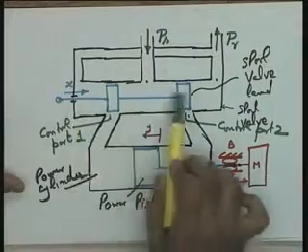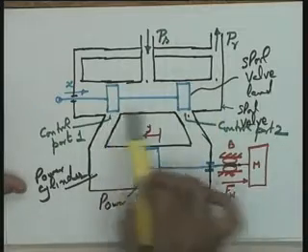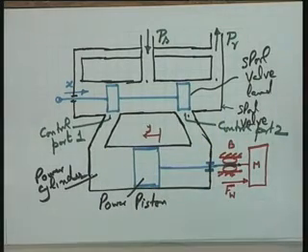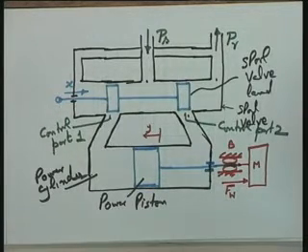Fine. Now let us go to the modeling of this particular device, unless there is a question on its working. If there is a small point, I hope during the derivation of its modeling that point may become clear. Otherwise, I welcome questions from you. In this particular case, I first assume the neutral position. What is the neutral position? The neutral position of the spool valve is the position which completely shuts off the control ports. See this point please. Step by step we will move, so that in a sequential manner we are able to derive the transfer function of this device.